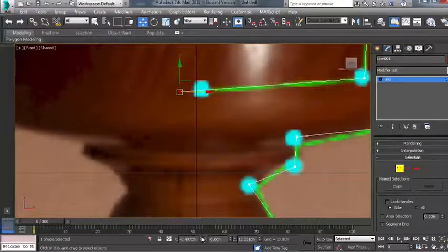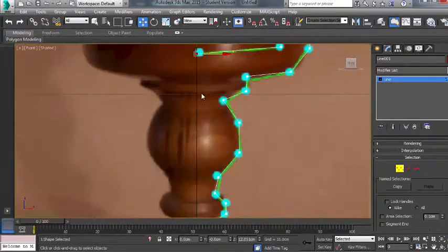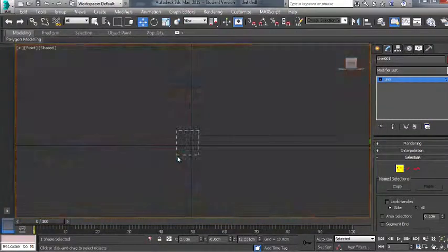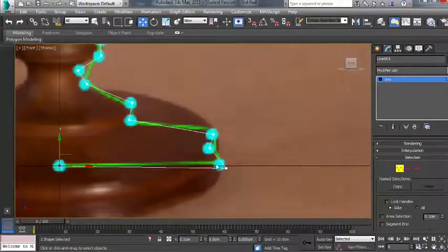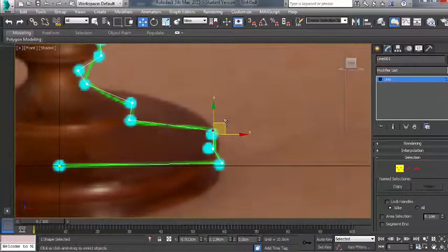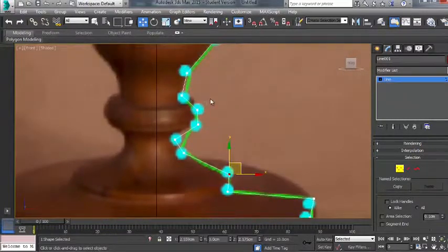So we can see, if you look down here, as you move it in and out, the X is actually changing. We want that X to be 0, so right click just to get that one on 0, and then we're going to do exactly the same thing with the very bottom one, right click to get that on 0, move it up and down. Then if you just go through each of the individual vertices, just make sure it is in a place that you would like it to be for your model. So whether it's lining up properly, or just making sure you have nice curves.